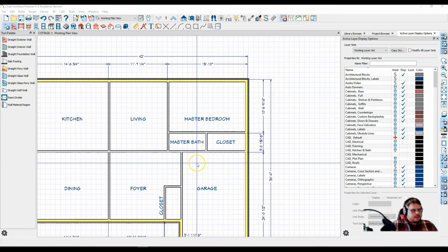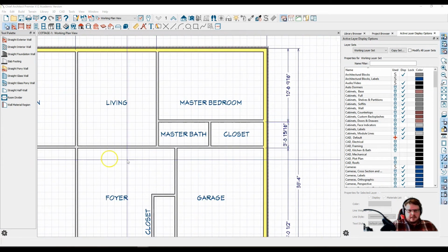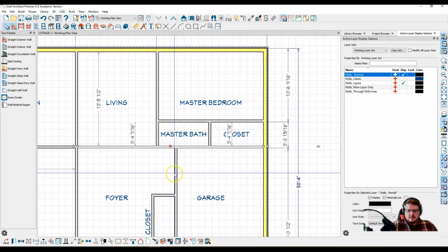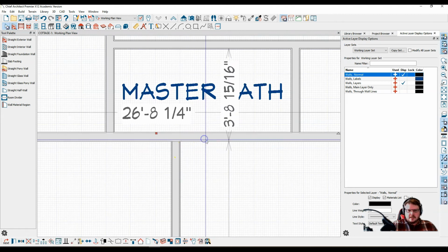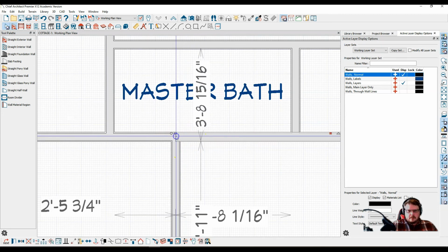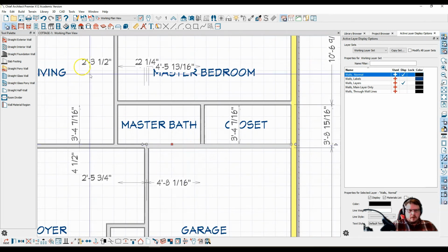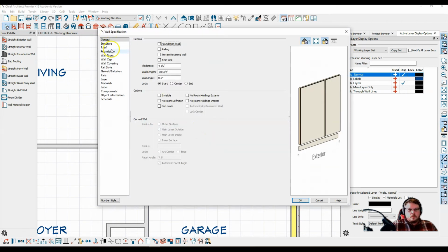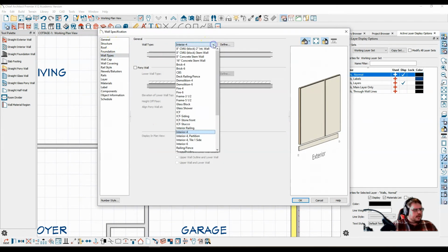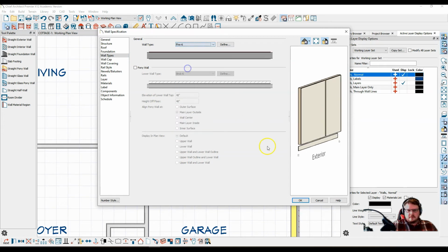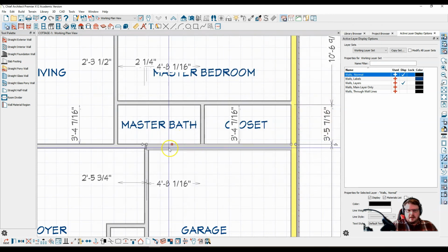The next thing we might want to do is define these two walls here as fire breaks. So let's select this wall and break it right here, and then select this one, and we're going to go into the open button down here, and we will go to wall types, and the fire is predefined. Here it is, fire 6. Hit OK, that has a fire break in it.